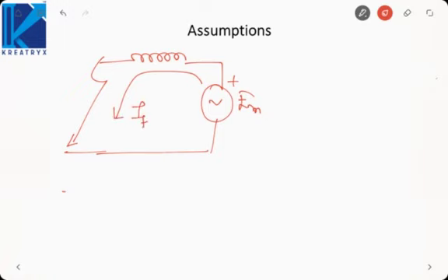Okay. Here the stored kinetic energy, because the rotor would have been rotating when the fault occurred, so it will have some kinetic energy stored in it. That stored energy will act as prime mover and it will be converted to electrical energy, which will be delivered to the fault. That means under faulty condition, the motor also acts as a generator and delivers current to the fault.